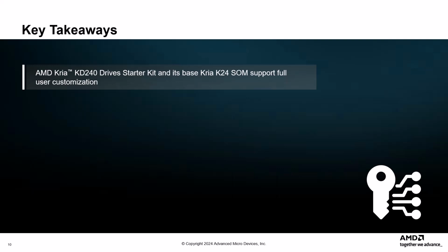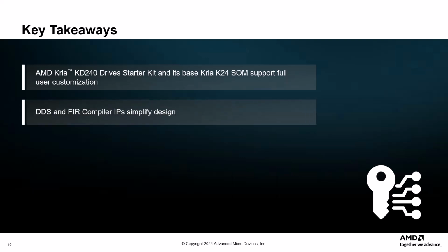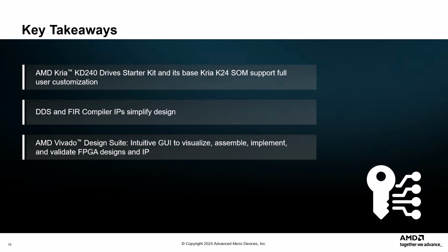The AMD Kria KD240 Drive Starter Kit and its base K24 SOM support full user customization through the AMD Vitis Unified IDE, customizable acceleration overlays, and AMD Vivado Design Suite hardware board files. The DDS and FIR compiler IPs simplify the design process. With the DDS, you can generate chirp signals for FIR filter validation, and the FIR filter requires only coefficient and hardware parameter specification. Finally, the AMD Vivado Design Suite provides an intuitive GUI for visualizing, assembling, implementing, and validating FPGA designs and IP.